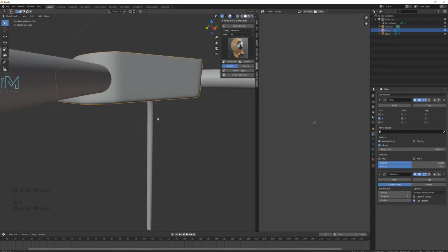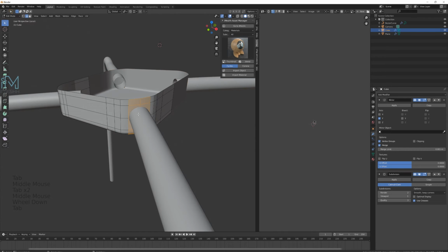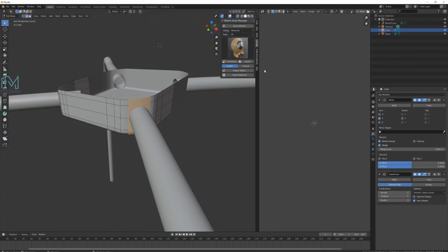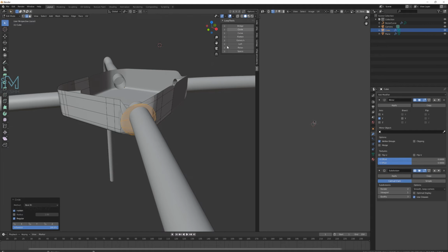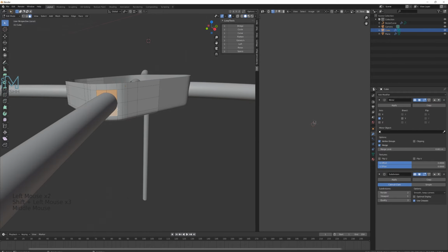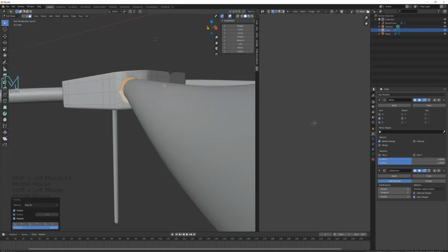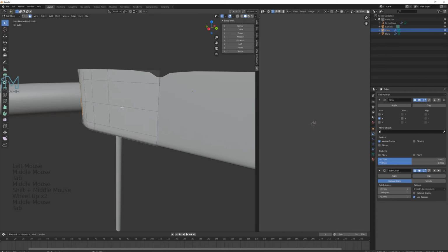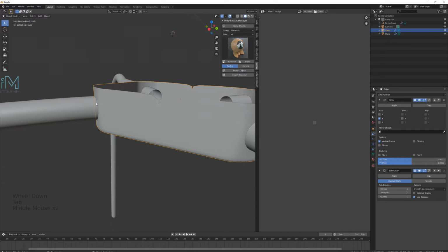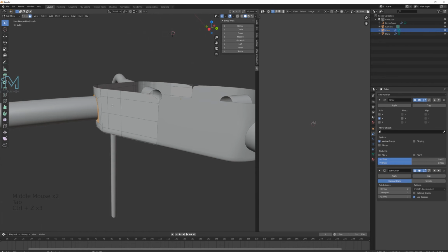Okay, nice. Now, if you go to Edit and Preferences, and click Loop Tools, make sure that's enabled. Then if you go to Edit, let's just select these faces. You can make this go into a circle, but the problem is that it deforms the mesh as well. Obviously you want this to be a circle but on a curve, which is the quite difficult part.